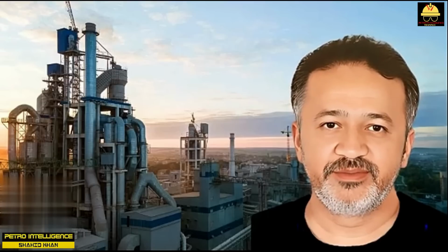For moderate temperature and low pressure condensers, such as vacuum surface condensers, a single pass on the tube side is not uncommon. These exchangers are typically fixed tube sheet designs. Such exchangers are fine from a purely process point of view. However, there is no practical way to disassemble the exchanger to clean the outside of the tubes, that is, the shell side. This inability to clean the shell side frequently leads to tremendous loss of efficiency after the condensers foul.